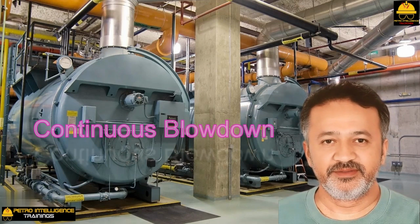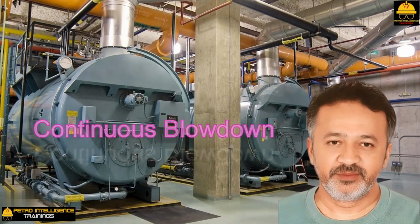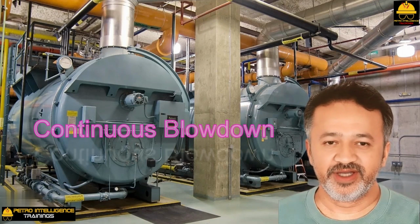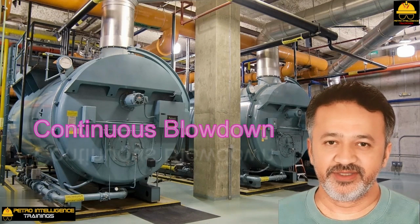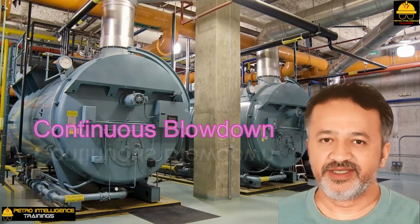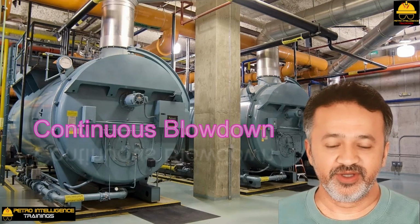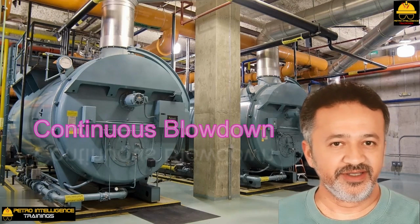Continuous blowdown. This blowdown water is best not drained from the very bottom of the steam drum. The concentration of silicates is 10 times higher at the steam-water interface than it is at the bottom of the steam drum. I've made the mistake in designing waste heat kettle-type boilers of locating the drain on the bottom of the kettle, which is wrong for the same reason.